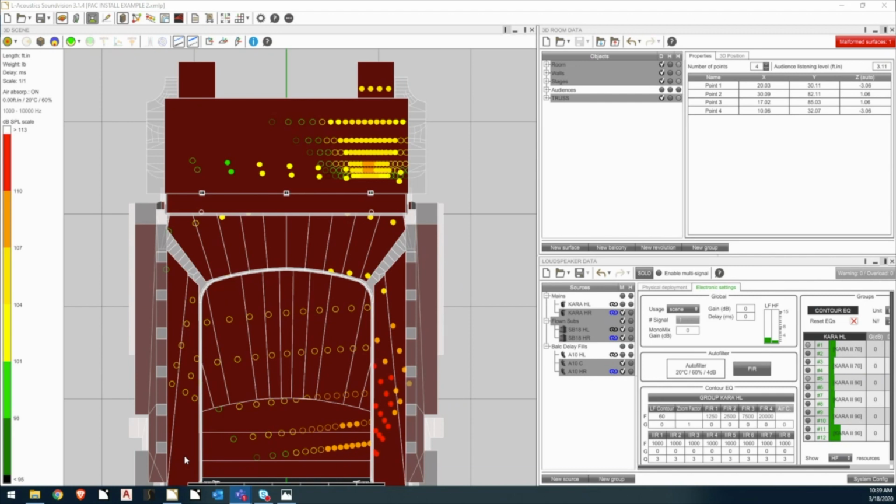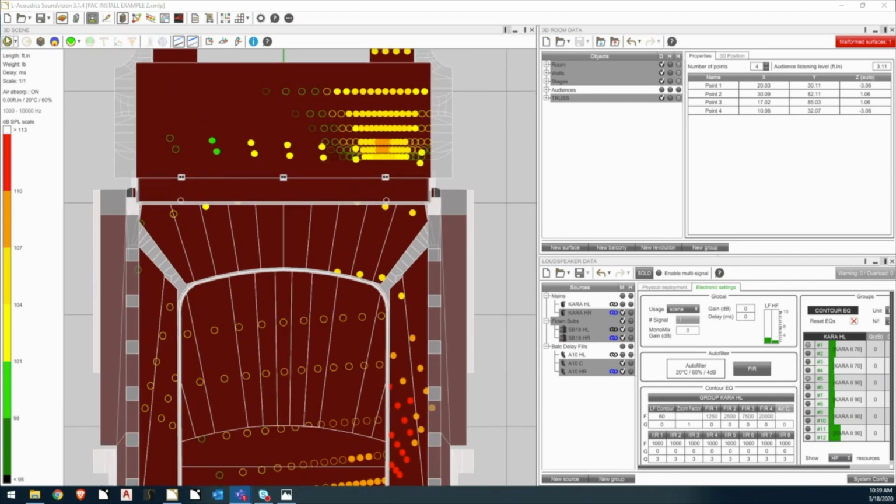So to the person who asked that question, when you delay sources in Soundvision, of course, we're properly time aligning, and that will change the results of what you get in terms of, say, the comb filter between 2 similar sources. However, one thing to remember is that they're only perfectly time aligned in, I believe, 1 spot. So only in that 1 spot will there be a significant difference. Everywhere else, you're still incoherent, right? So it's not that big of a difference. And we can probably show that if we want and turn the delay on and off, Jesse. But I don't think it'll make a huge difference one way or the other in terms of the mapping results.